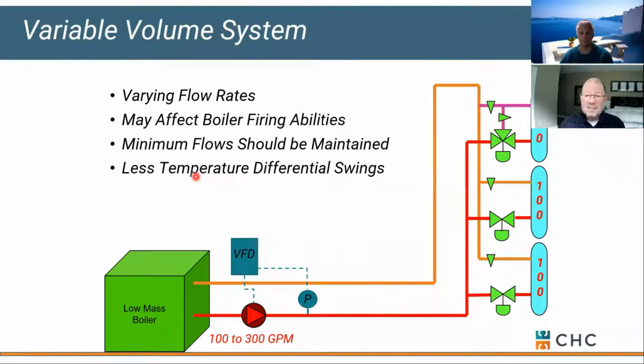So that's the importance these days. We've got two-way valves out in the system, typically controlling on pressure or differential pressure, and a drive that's picking up the change in pressures as our two-way valves modulate, and we fluctuate our pump speed accordingly. As we do that, we're also changing flow rates.